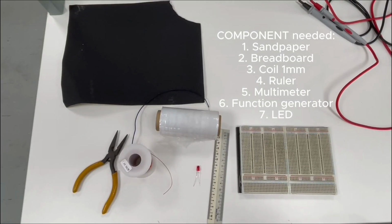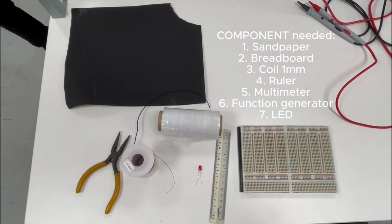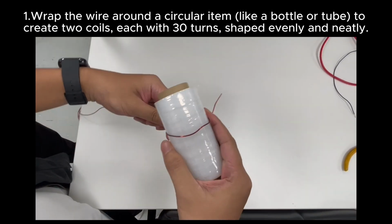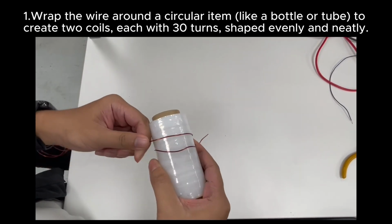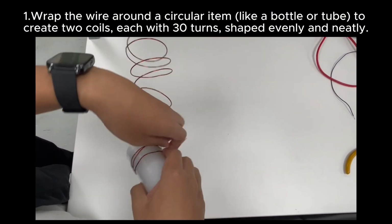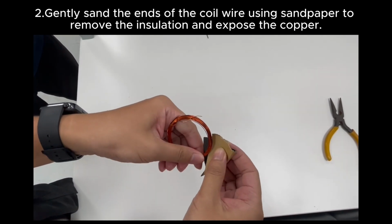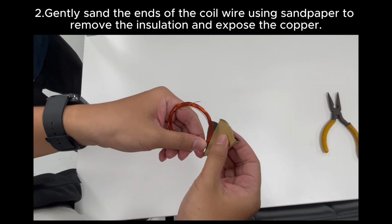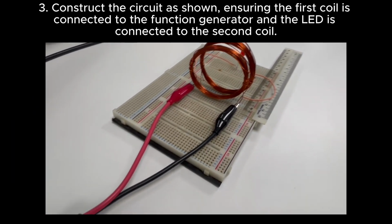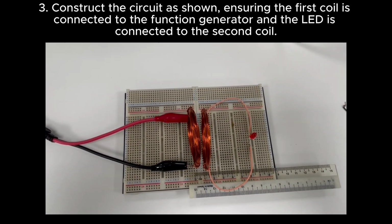To start the experiment, we need all these components: sandpaper, breadboard, coil, ruler, multimeter, function generator, and lastly LED. For the first step, wrap the wire around a circular item like a bottle or tube to create two coils, each with 30 turns shaped evenly and neatly. Second step, gently sand the end of the coil wire using sandpaper to remove the insulation and expose the copper. Third step, construct the circuit as shown, ensuring the first coil is connected to the function generator and the LED is connected to the second coil.